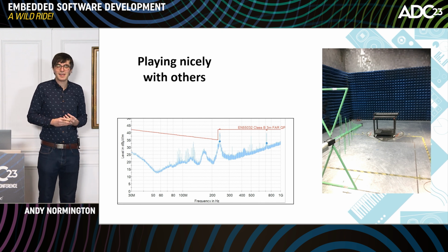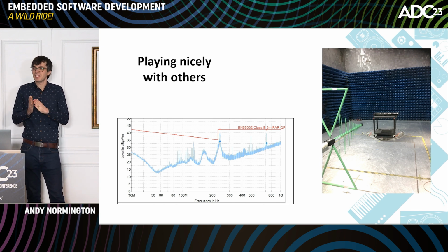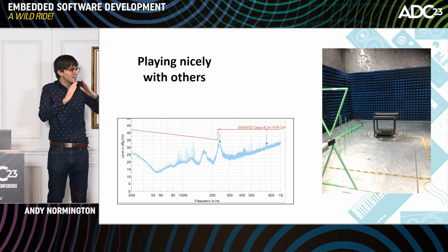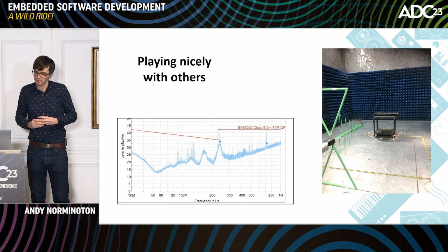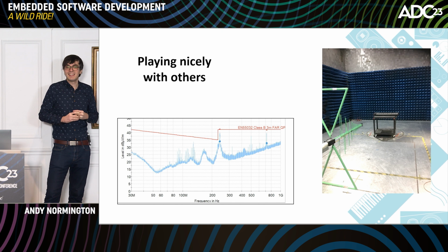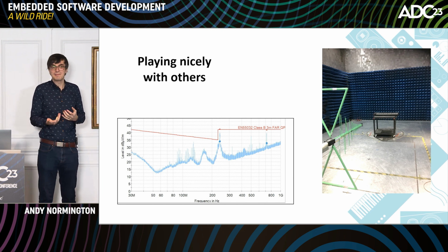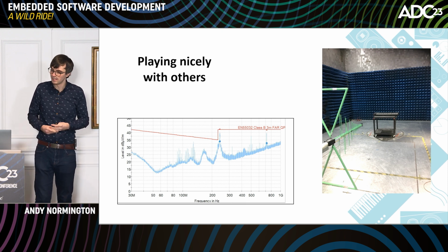There's a trick we can pull out in some microcontrollers called spectrum spreading, where we can modulate the core clock of the microcontroller just a little bit, and that helps us to bring that peak down and spread it over an area of the spectrum, so the energy is spread out over some frequencies. Not every microcontroller supports that, and when we do that, we have to be careful then that we don't mess up clocks that we need to be more stable, like audio clocks and USB, so it increases the complexity too.